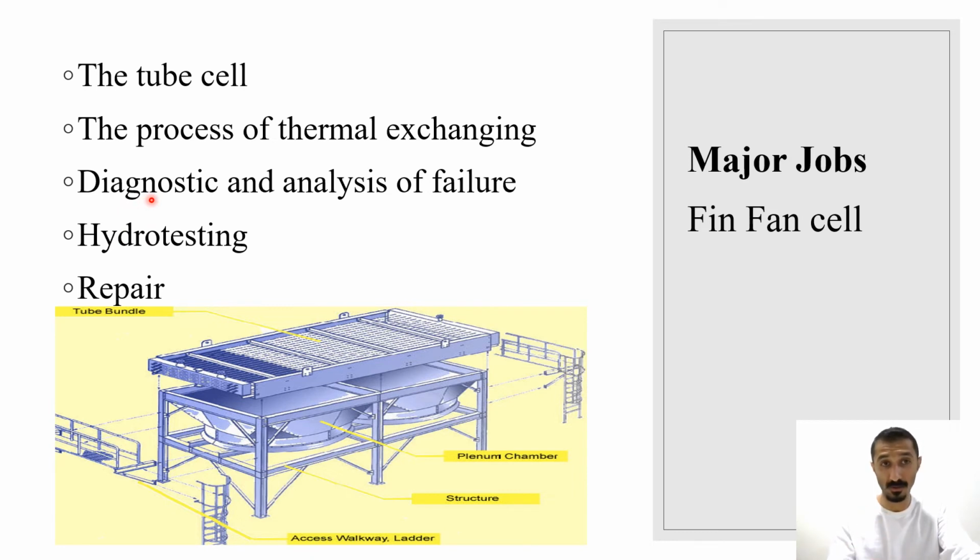I did diagnostics at my internship, diagnostics and analysis of failure. The control room sensed a failure of the turbine of the fin fan tube cell. It says that we have high temperature on this specific tube cell, so I go out, I do diagnostics, I isolate it, and then I do my repairs. I hydro test each tube from here.